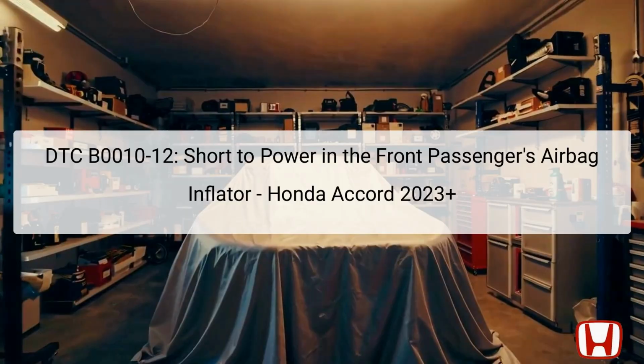DTC B0010-12 indicates a fault related to the front passenger's airbag inflator system in the Honda Accord 2023 model and beyond. This code signifies a short to power condition in the airbag system, specifically related to the first inflator.